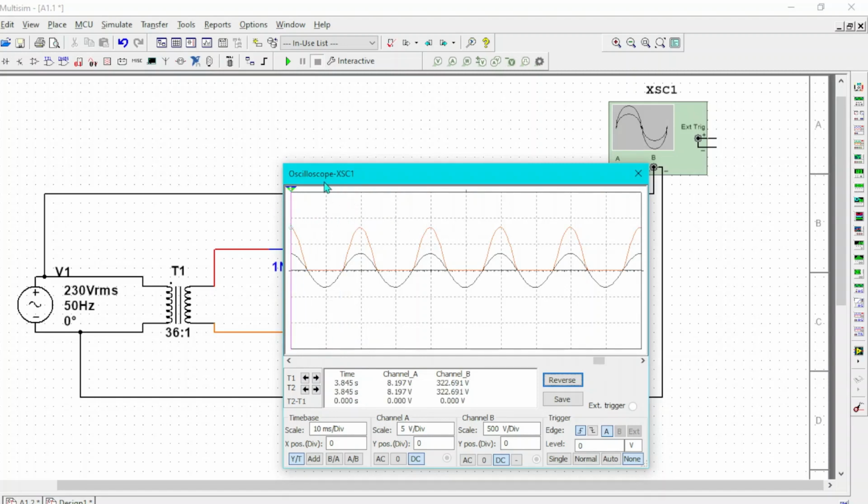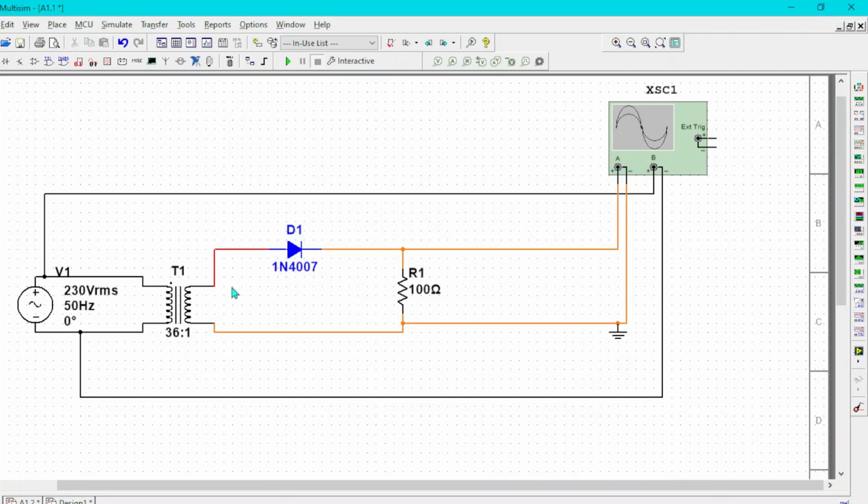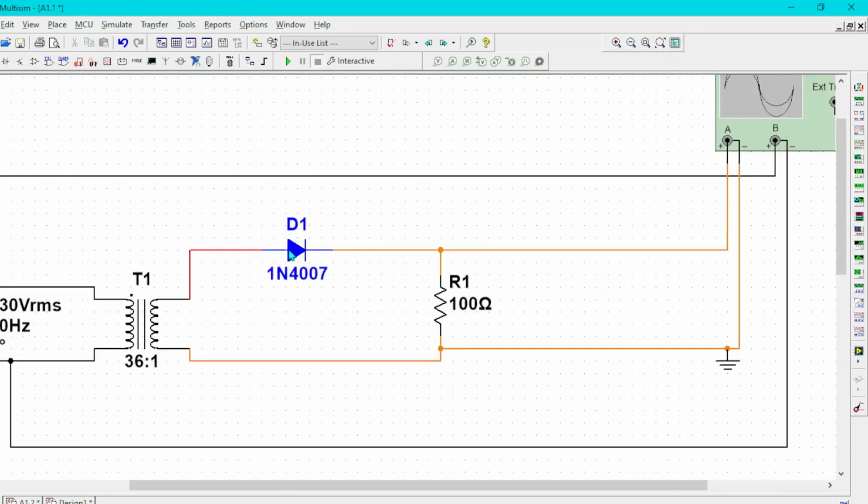We will not go into much detail on that, but what it does is that it cancels out the negative part of the signal so that we can easily work with only the positive signal. There are many different ways of doing this. You can either shift the whole signal a bit above, or you can just cut out the negative part, as we have done right now. What you have to understand basically is that the diode is in a particular condition wherein it will only allow the current to pass through one way.